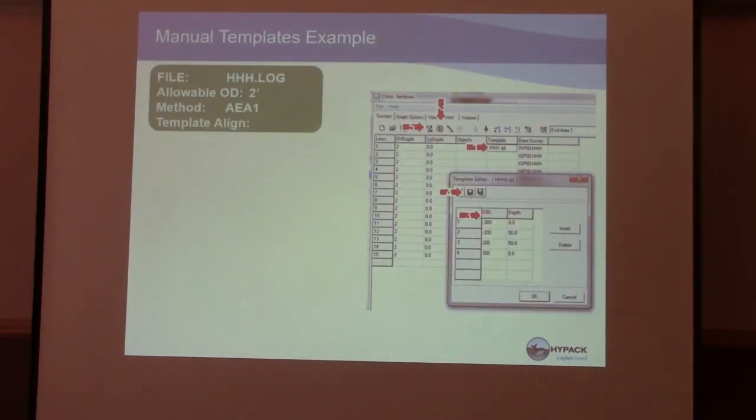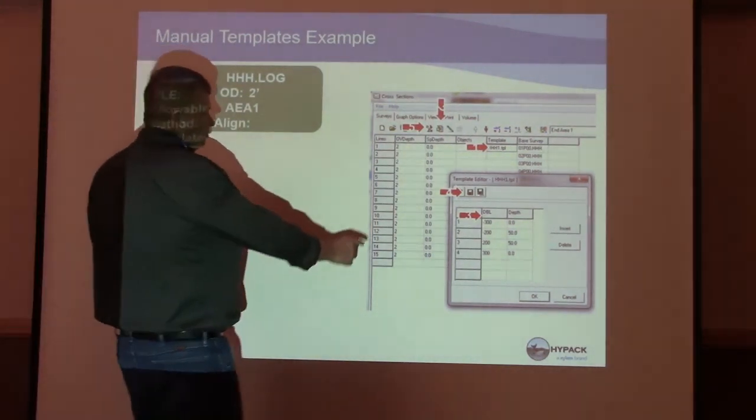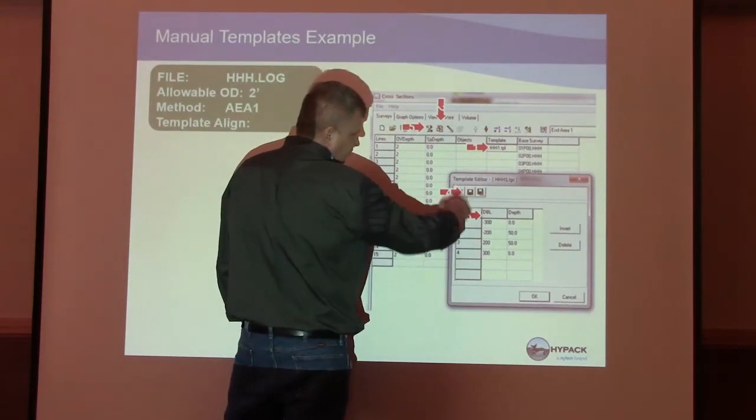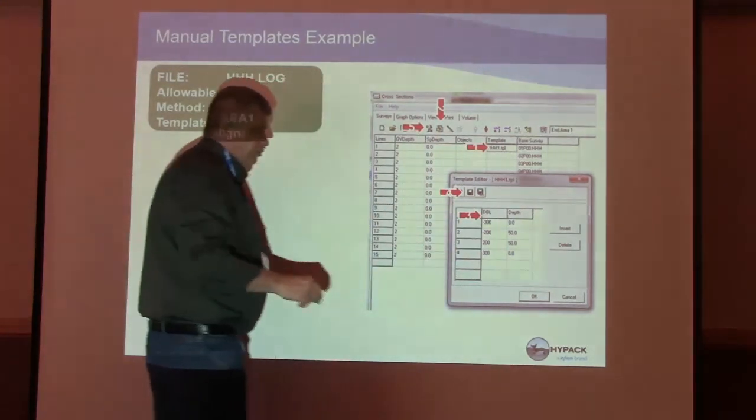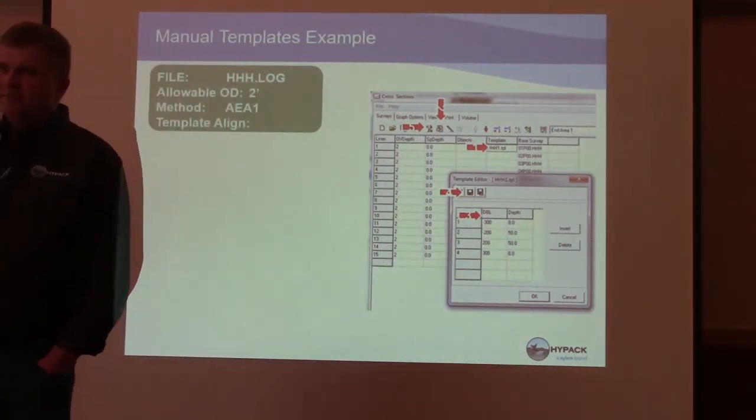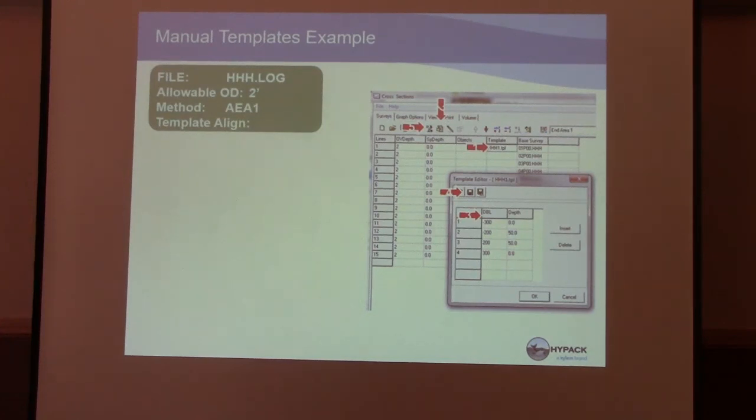When you run the template editor program within channel or cross sections and volumes, you click on this button and it brings up the dialog. You have to know the DBL and the depth. So you say so many feet down and this is my depth, and so many feet down and this is my depth. It's a very long way to do it, but sometimes you have to build a template per station, especially on beach jobs. Beach jobs sometimes have varying benches that you have to make up. Sometimes you'll have to do it in here.